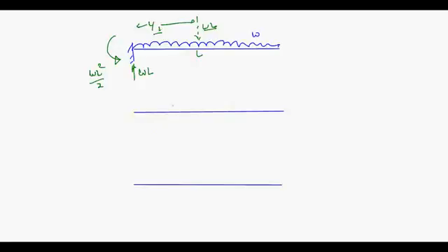Now let's start with the shear force diagram. One thing I know for sure, that my W is equal to dV by dx. W is constant and it is negative, so I am writing minus C is equal to dV by dx. If you integrate it, you will get V is equal to minus Cx plus C2.